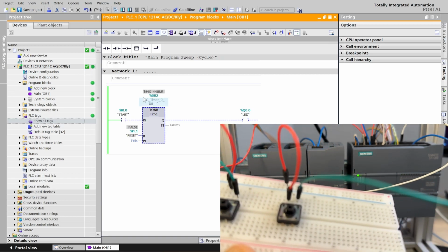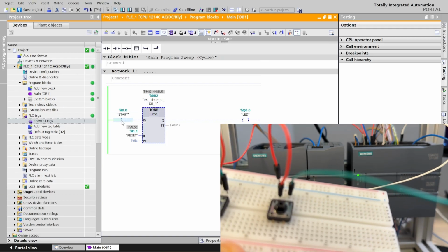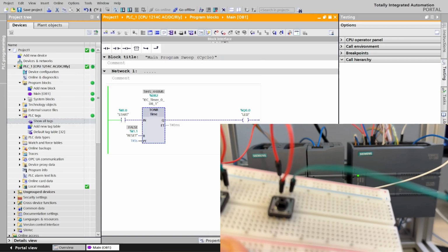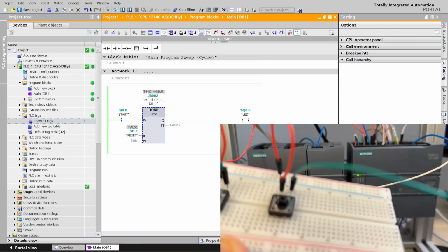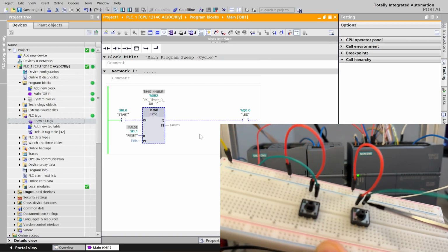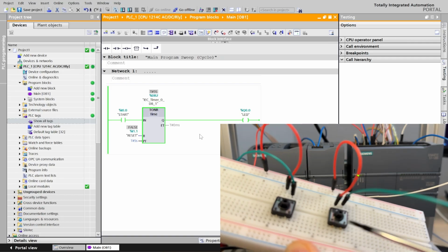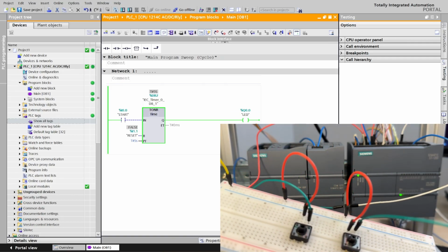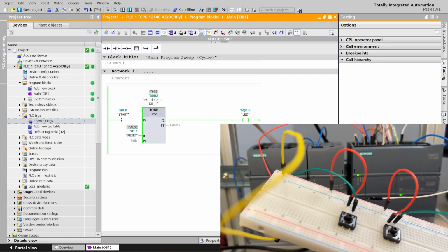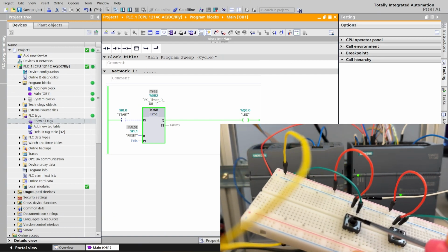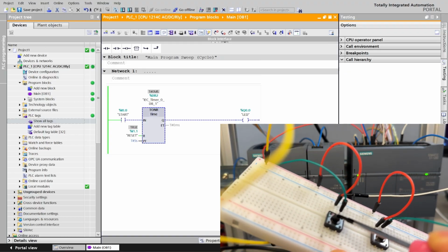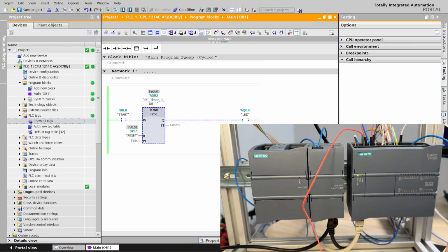it will count up how many seconds it was pressed, but our output is not on yet, right? Like when this time reaches 5 seconds, then our output will turn on. So let's press and make it 5 seconds, and you see our output is on. Here it's on. It stays on until we press the reset. You see, when I press reset, then it turns off.